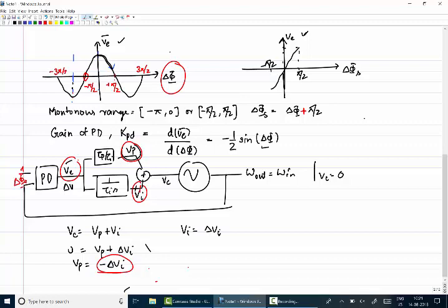It's non-zero, but it's not changing. I know that someone will pick up. If you have a non-zero value at the input of the integral, then that integrator will keep on rising, and let's say it has saturated. Let us say the integral has a finite gain, meaning what you are saying is right. If I have this as a pure integrator 1 over S, then there is no other condition other than V error average equal to 0. There is no other condition.